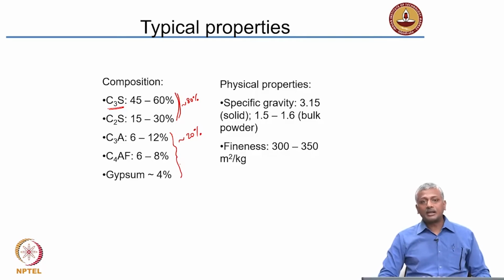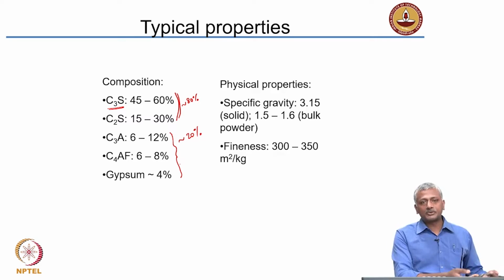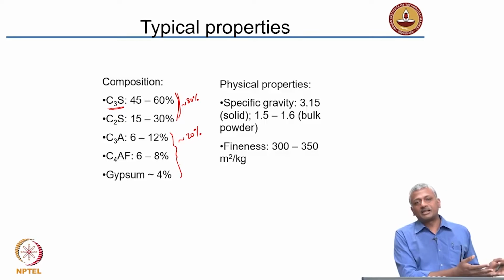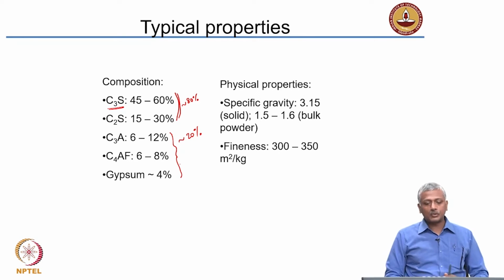Okay. We talked in the last chapter in stone, brick and mortar about hydraulic lime, right. Hydraulic lime is basically produced from impure limestone, burning of impure limestone. Again, that leads to the formation of calcium silicates. It forms smaller forms of calcium silicate. Here it forms larger forms of calcium silicate like C3S and C2S.